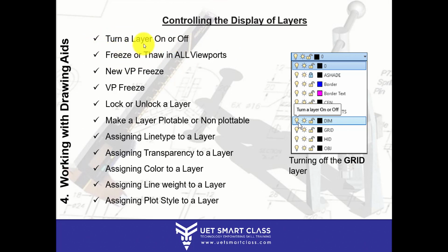But there is a major difference between layer on/off and freeze. When you check your AutoCAD system, for example, if you are working, your AutoCAD becomes heavy. Your KBs, basically your bytes, are being used. Your space is being used when you are making so many layers. Sometimes even if a point is there in that particular layer, the layer cannot be deleted. That's the complication with layers. So you have to work very safely with layers.